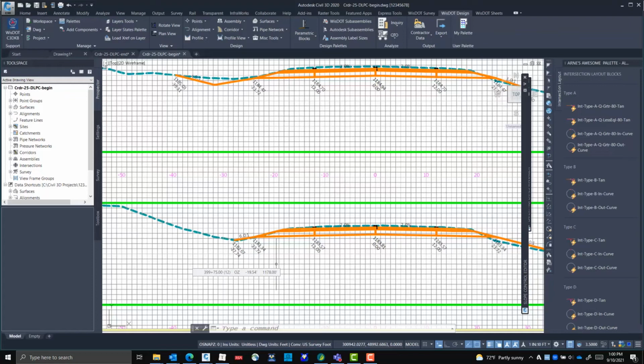They've got to be able to say, I want this section to be a ditch, I want this section to be a fill, wherever it might be. So one of the things that we added to this subassembly, we call it a ditch fill switch. If the value of the switch is 1, it's running on automatic. So it works just like most daylighting subs, where it's going to make a ditch if it's below ground, and a fill section if it's above ground.